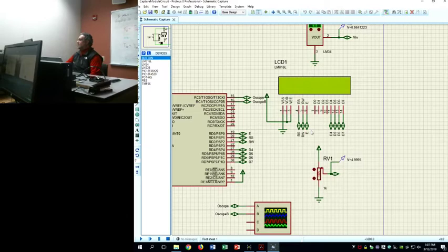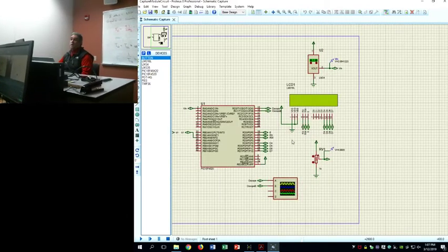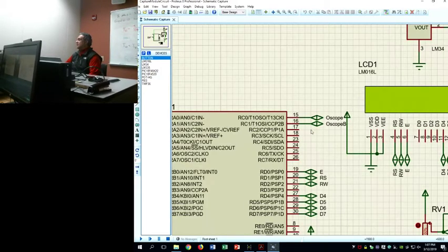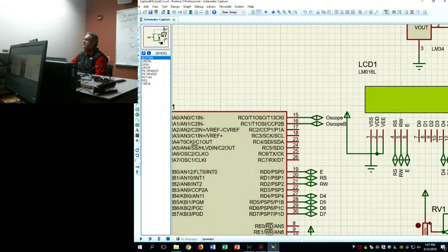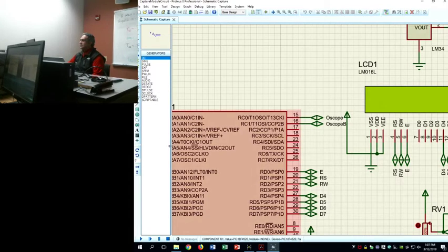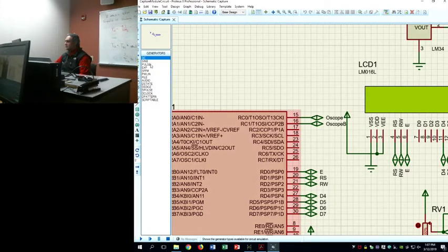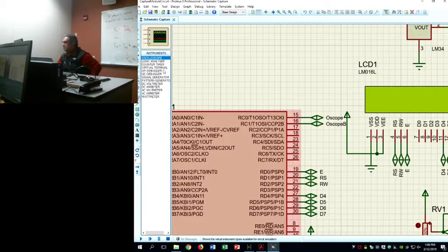Because this guy is already working. Now, the only thing that we have to work on is our signal generator, because I know that on C2, that's my input. That's where CCP1 is located. The signal generator is actually found, there's this little button that looks like a sinusoid. And so I believe that in here, you can find your signal generator. Let me see. Actually, no, I think it's down here. Oscilloscope, logic analyzers, signal generator right there.